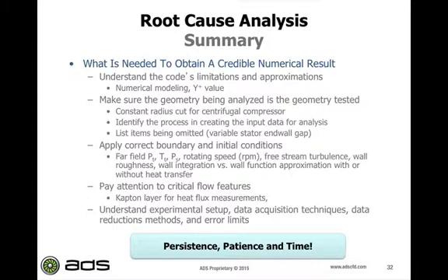differences. Okay. What we would recommend is that if the geometry being analyzed and what is being tested are different, it's important to list out those items. For example, whether or not something has a variable state or end wall gap, things like that. Next, we have to make sure to apply the correct boundary conditions and initial conditions. Okay, and we have to make sure that the location that we are applying them are the same between the experiment and our CFD.